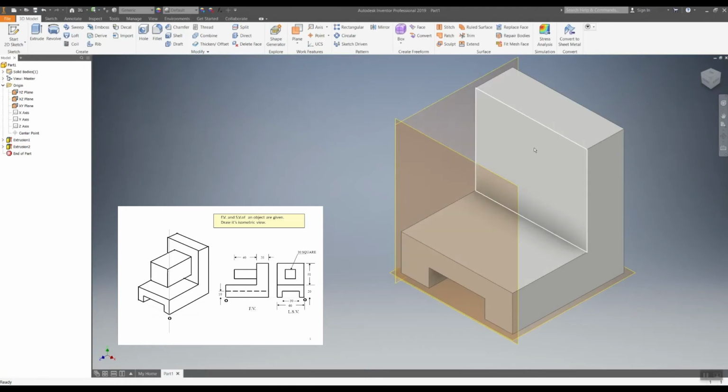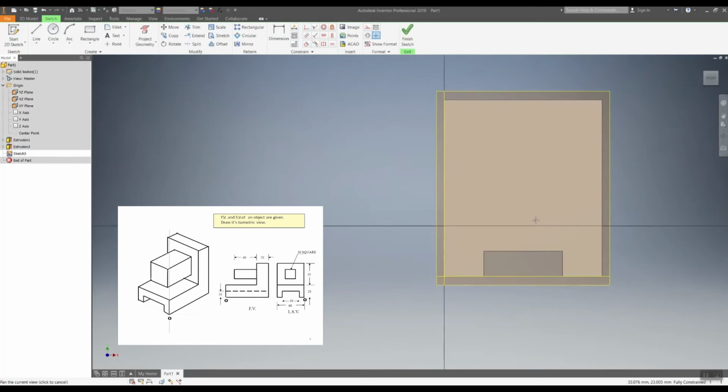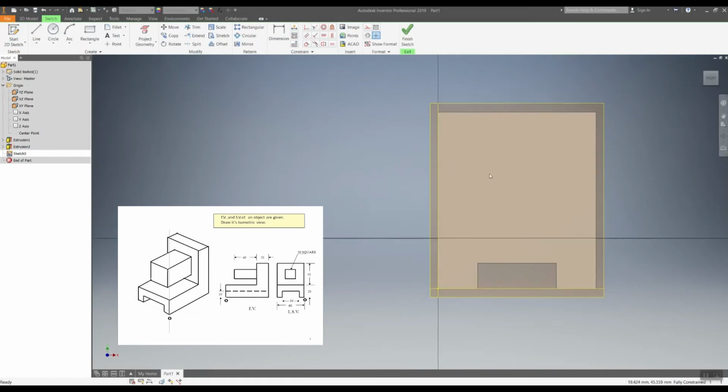I want this box to come out of this part right here. So I'm simply going to go Start 2D Sketch. Click on this box. Let's start this sketch here. We have a little math to do. Across, this object is 60, and my square coming out is 50. So that means 60 minus 30 gives me 30. I have to divide that in half. That means my line has to be 15 over and 30 long.